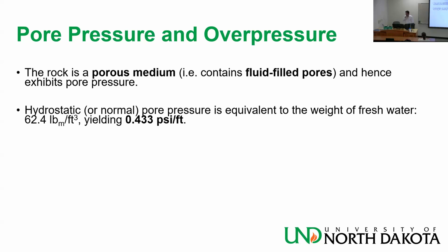This is not like the lithostatic gradient, which is an approximation. If I don't have any indication, 1 psi per foot makes sense to use. The 0.433, you don't use it unless you are told to use it. So 10 feet of fresh water is 4.3 PSI, right?